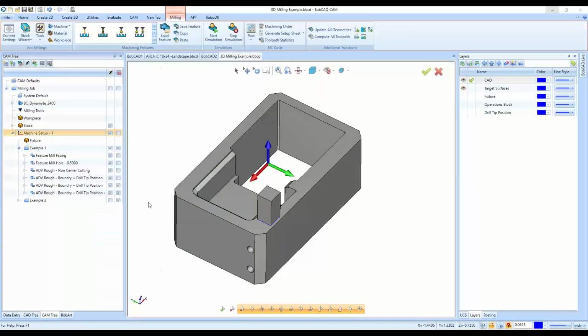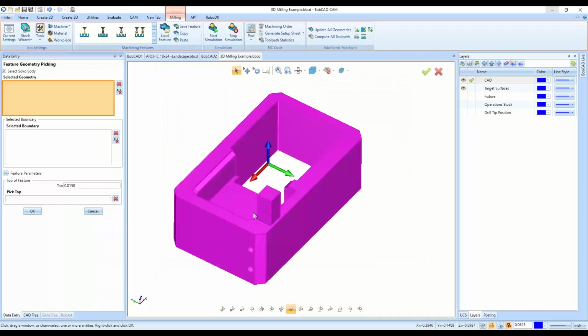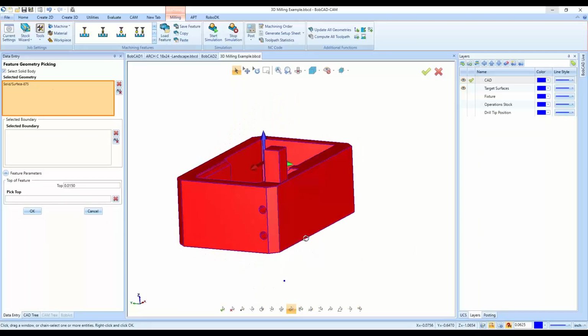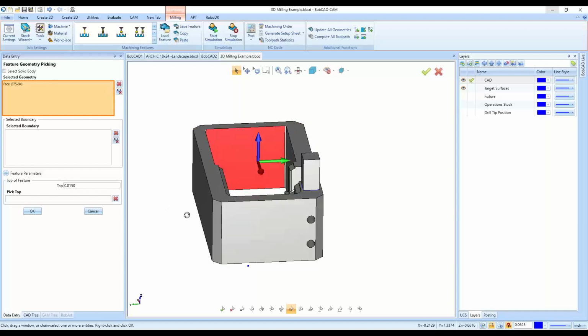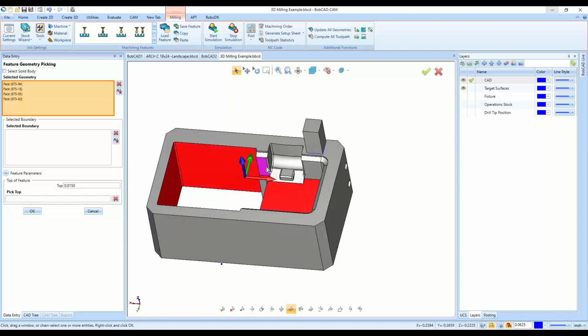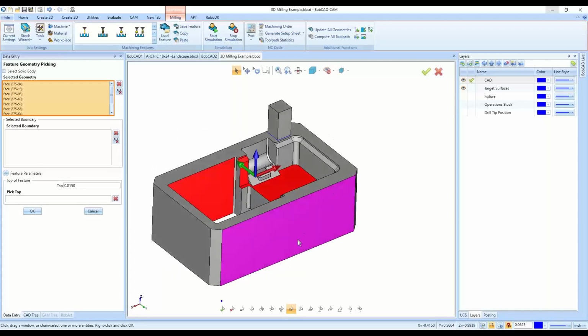And mill 3-axis. Select geometry. So here's this visual representation. If I'm doing just the milling on the inside of this pocket here, and I selected, for example, just the surfaces on the inside, all of them on the inside, I'm telling the software, hey, I just want to pocket this. The software does not understand anything here related to the 3D model also. So it doesn't know you need to avoid this boss here as well.